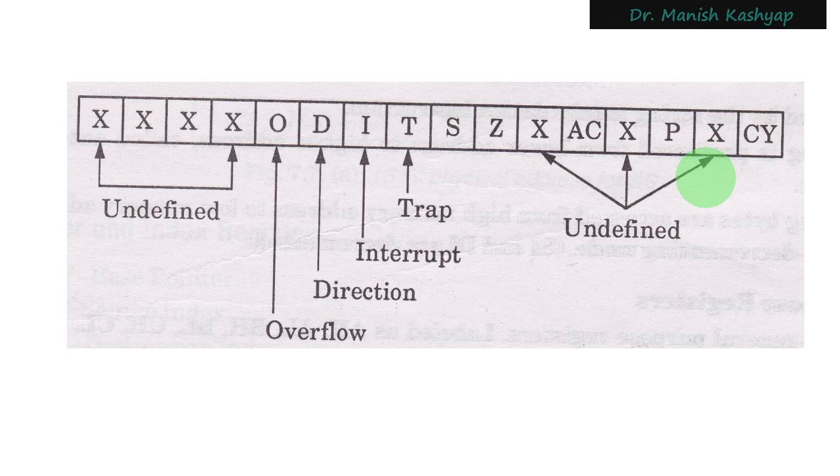The programs which work in 8085 might also work in 8086 if you use appropriate commands, because there is no change of this flag structure, as you can see here, right? So this sort of maintains upward and backward compatibility here. And these three don't cares are also placed at the exact same locations as they were in 8085.